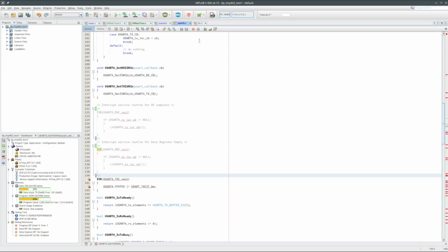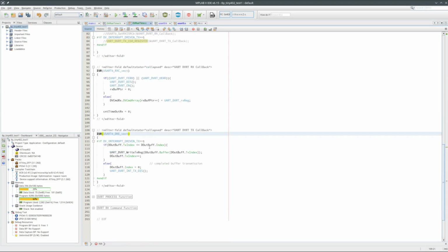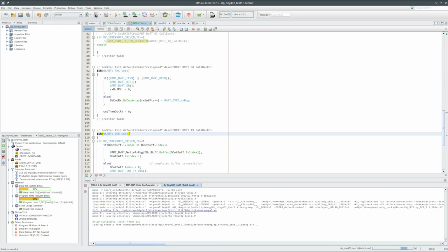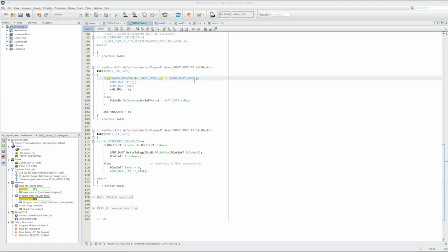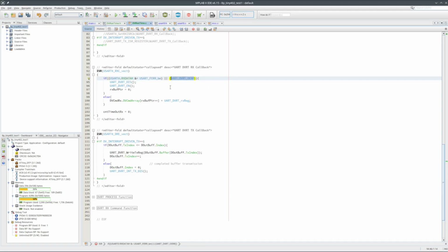The receiver might work with the defines I have in place, but the transmit is not going to work. But I will try and compile, make sure I have everything in place. I'm going to replace these defines with the actual values. I find it easier to follow what's going on with the microcontroller's registers that way. Maybe not as easy to move code around, but this is a I'm getting to know the tinyAVR 0 chips project. So for the receive complete interrupt, there are a few items to replace.